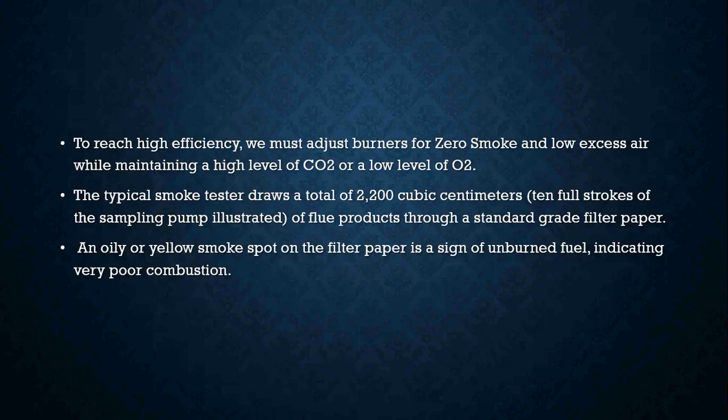To reach high efficiency, you must adjust your burners for 0 smoke and low excess air while maintaining a high level of CO2, or a low level of O2.